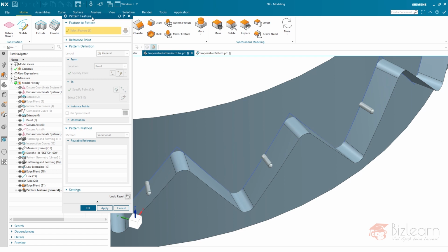But the line cannot exist without the reference to this surface. And that's the reason why we are using the pattern feature here, because each instance of the feature is still a feature. It's still driven by parameters. And one of the settings within the line, meaning the relation to the surface because of the direction, is still there. So I think this would be the explanation why it's not required here to reuse the normal option.